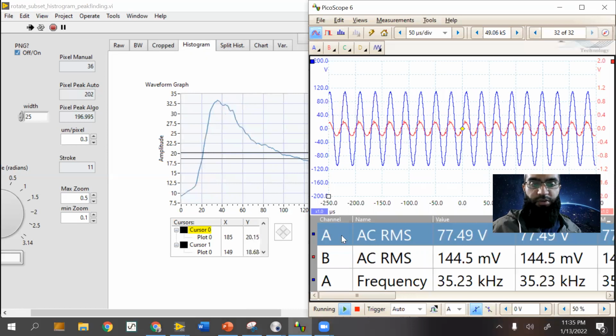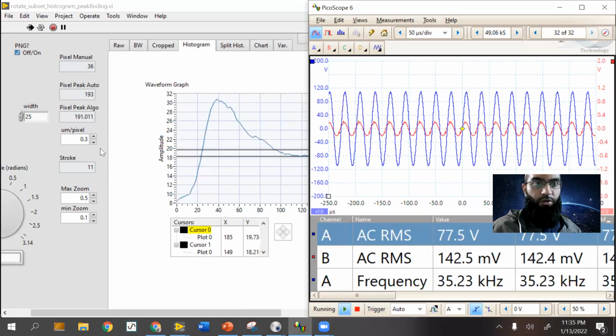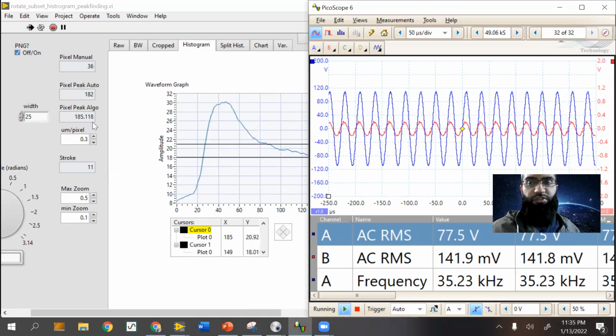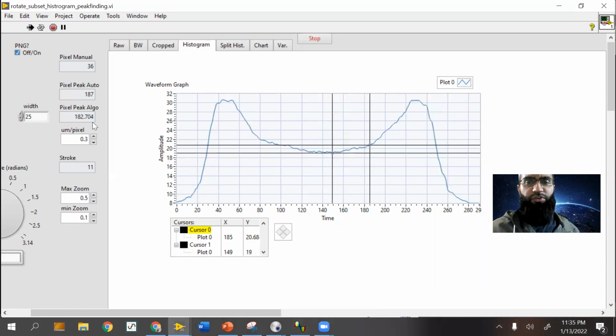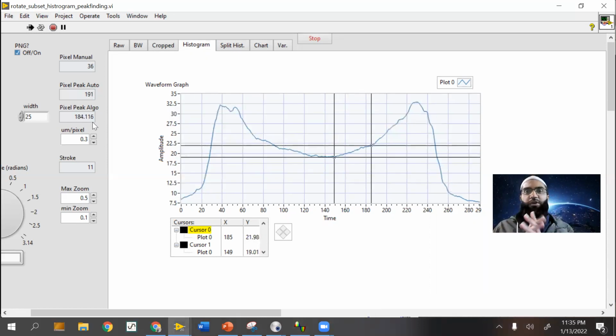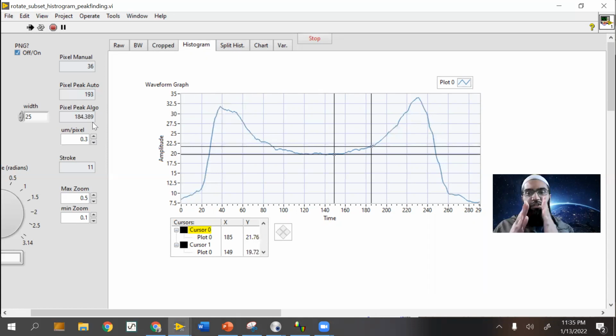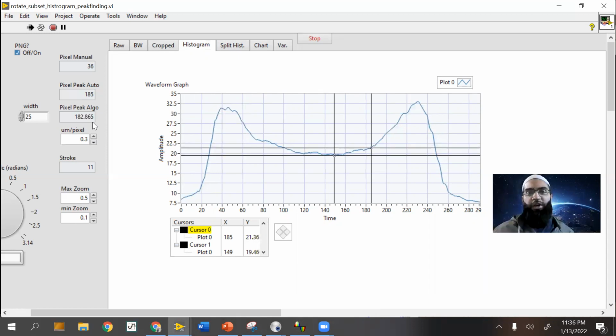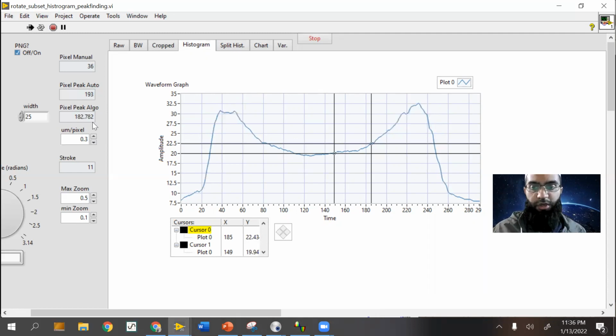And now we're at 77 volts, and we're at 185 versus about 130. So it's not necessarily tracking voltage linearly, because as voltage increases, the resonant frequency shifts away, so you're not going to get as much for voltage, but current would more than likely be similar.